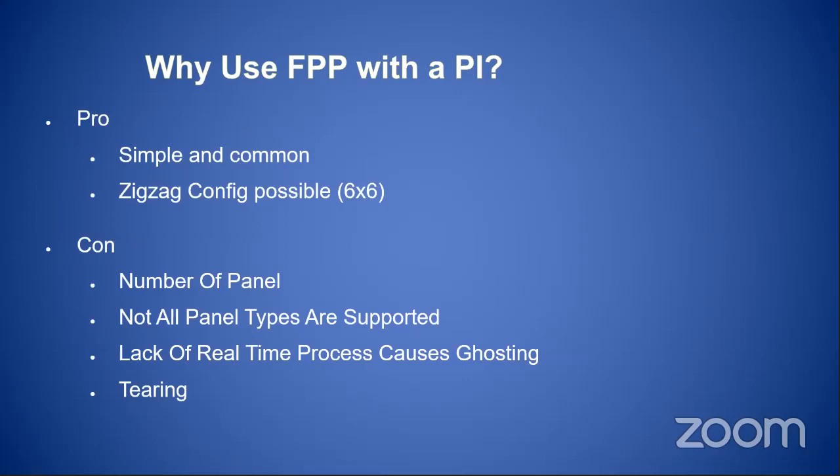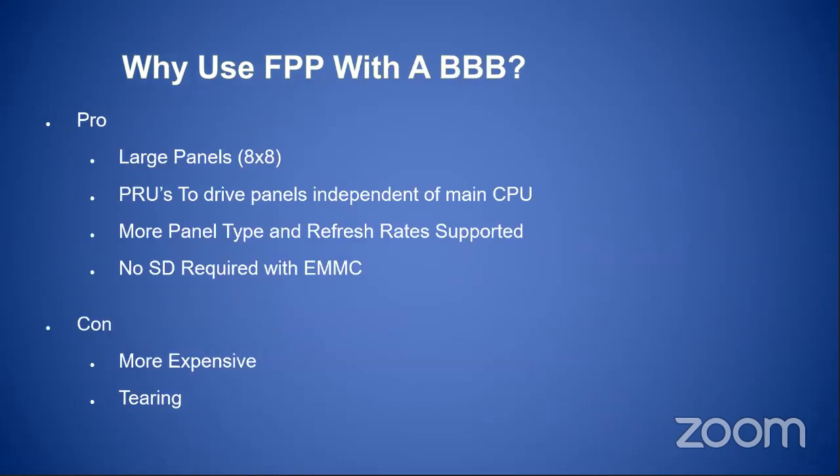I never recommend a Pi to anybody. Whenever they say they want to build a panel, I say either go with the BeagleBone or go with a Colorlight. I only recommend a Pi if they say, well, I already have a Pi and I just want to use it. I say, okay, well then a Pi hat will do it. But other than that, I don't ever recommend a Pi, just because it does lack the real time and not all the options are supported.